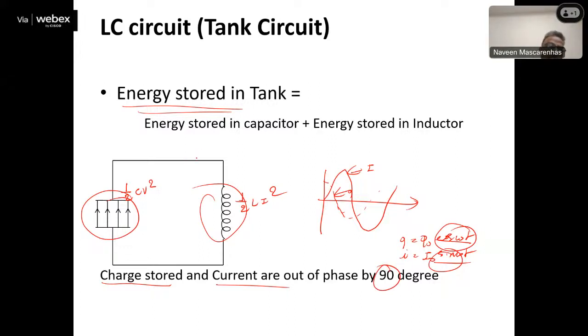So this is the tank. The advantage of connecting a coil in parallel to a capacitor is always to generate oscillations. But what we get in this is damped oscillations. Damped oscillations means oscillations whose amplitude goes on decreasing and finally dies out, because there are losses in the tank, losses in the form of invisible radiation, and yes, these wires have got resistance, therefore dissipation of energy in the form of heat.